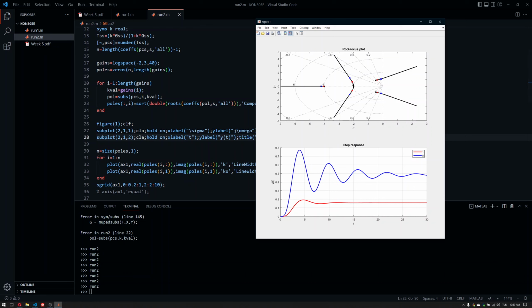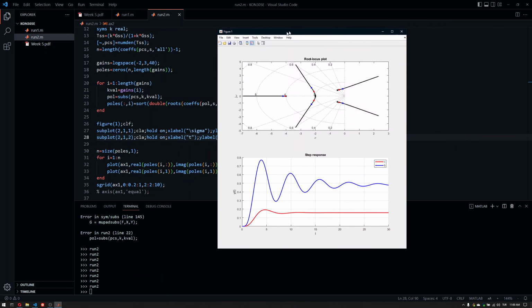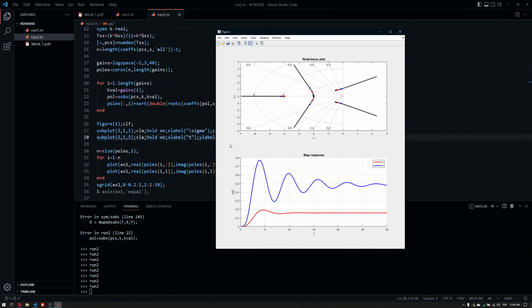One of those things is basically if you increase the gain in a certain closed loop where we have a P-type controller, then the system becomes faster and becomes more stable. As you can see, this root locus plot here proves the inverse. You can see increasing the gain for this system is not good at all. So coming up with general statements is not always true, doesn't hold. We have to examine the root locus plot in order to conclude such things.